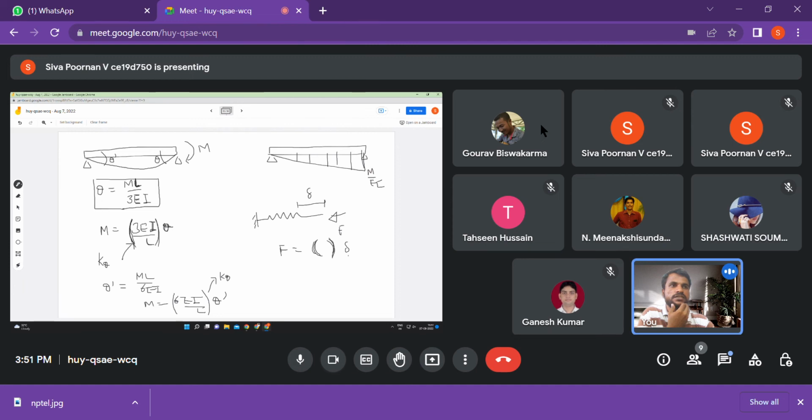Okay. So we need to define where the rotation is, where the moment is, and so on. So for a given moment, given location of moment and given location of rotation, we can find a relation between them using the force methods that we have already studied for any system. Now we have seen determinate systems. For indeterminate systems as well, we can do that, right? So by that we can find out what its stiffness is. Why is it so useful? We'll see later, subsequently.